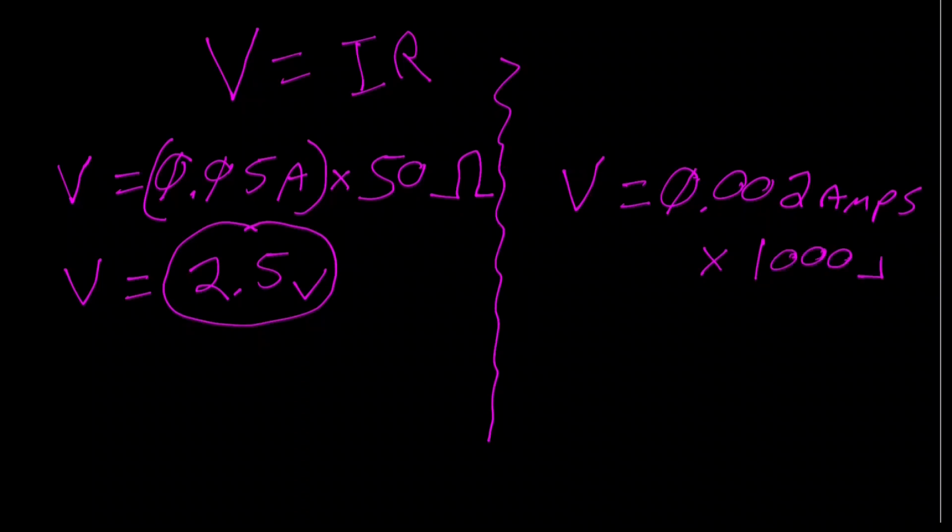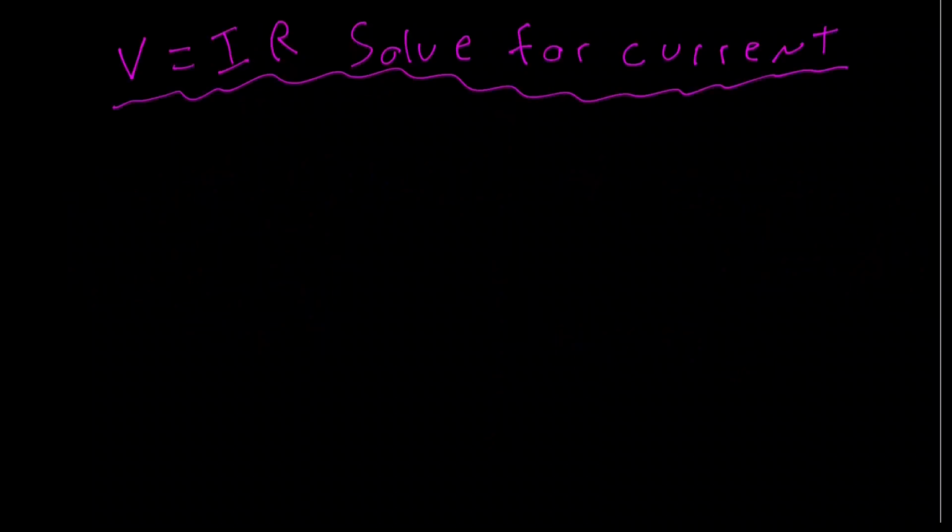And if I didn't mention it, you can see the value. The symbol for ohms is an omega. So that's the ohm symbol right over here. That's the symbol for ohms. And if we do the math or put this into our calculator or just do it ourselves in our head, we see that this gives us a value of 2 volts. So with a 1,000 ohm resistor and a current of 0.002 amps, the voltage across that resistor will be 2 volts.